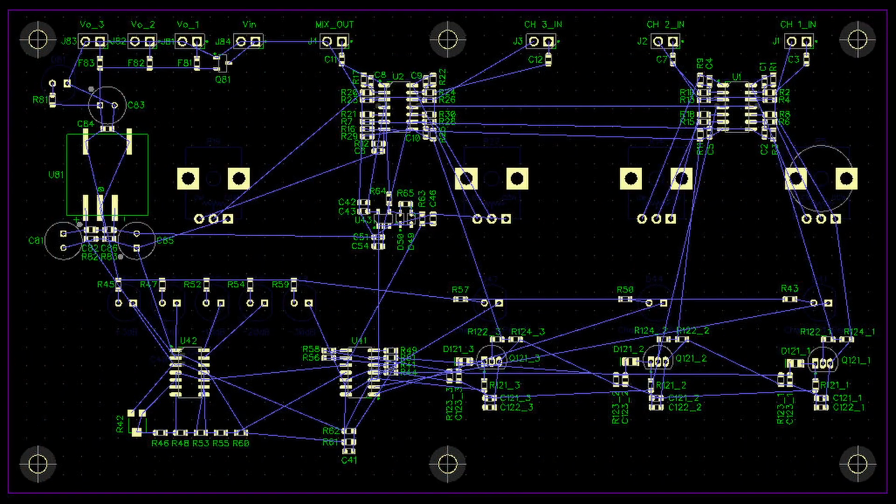One note, the components associated with the input pins of op-amps should be placed as close to the op-amp input pins as possible to avoid creating antennas for noise and interference. I'm not going to have you watch this whole process. Instead, here are the finished results of component placement and reference designator beautification.